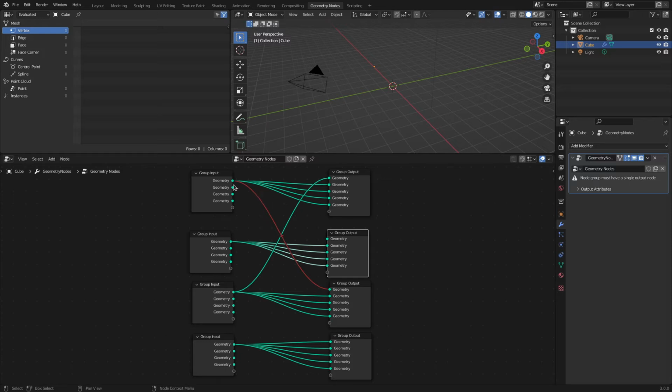Now you'll notice a muted link is red with a little kind of hash mark across the link. So if I wanted to mute all of these, Control Alt, right mouse button, drag, mute. Everything's muted. I accidentally also unmuted the link that I originally muted, so just be aware of that. Now what muting actually does is, for most practical purposes, it disconnects the link without actually disconnecting the link, leaving the actual link there, disconnecting the data throughput.